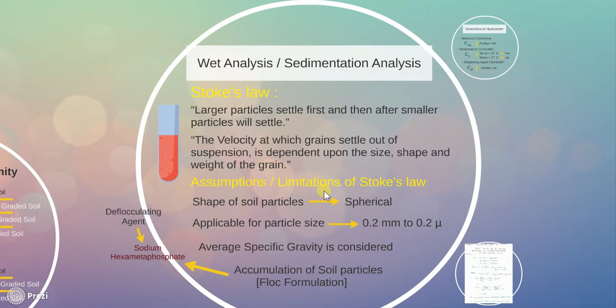The analysis with Stokes' law is based on the assumption that the falling grain is spherical, but in soils the finer particles are never truly spherical. They are usually flaky or needle-shaped. They do not settle out of the suspension in the same manner and at the same rate as smooth spheres. Thus, the sedimentation analysis gives the particle size of equivalent diameter.